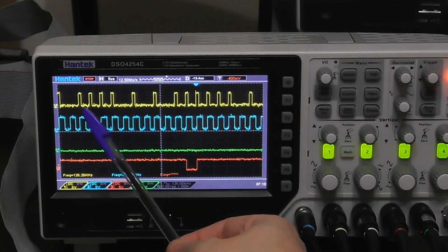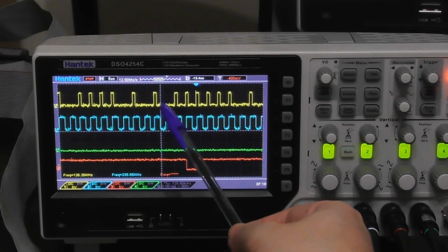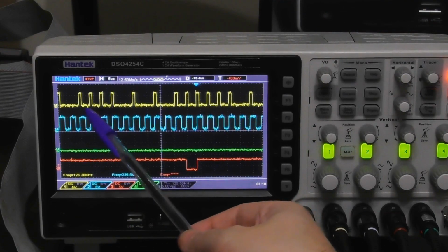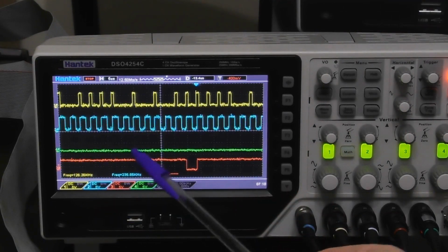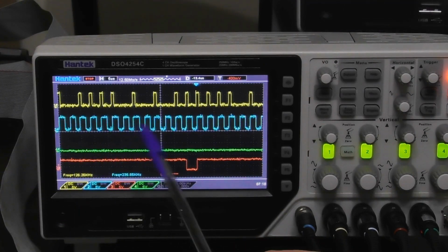So the clock bits for this one are 1, 1, 0, 0, 0, 1, 1, 1, so that's correct, that's C7, and the data byte is probably either FE or FB, depending on whether this is a sector ID or actual user data.